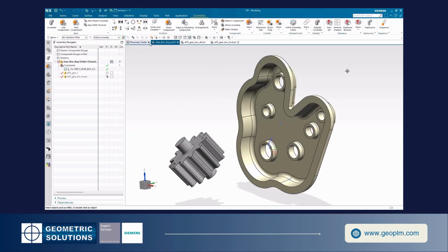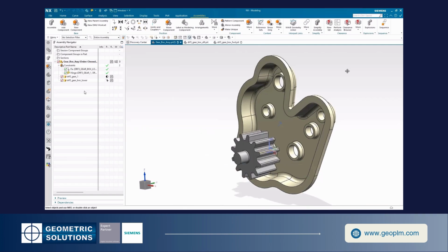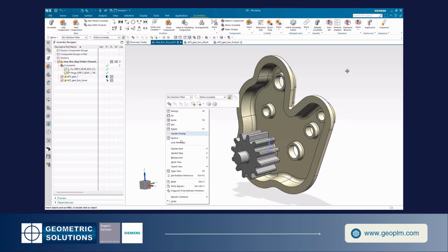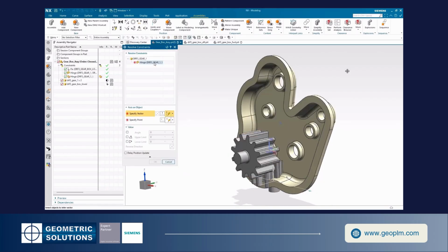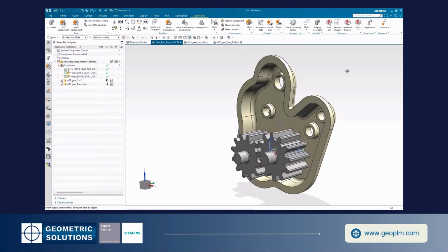Here we have a gearbox assembly, and the gearbox already has a fixed position. I will now add a hinge joint between the gear and the gearbox. Let's add one more instance of this gear component with a new hinge; this will show that the external joint references need to be satisfied. As I copy and paste the gear, the constraint dialog will appear, and we see that an unresolved hinge joint shows in the list. Using the dynamic dialog, let's define the vector and the center point of the hole for the gear hinge to rotate. From the Assembly Navigator constraint listing, these constraints are resolved.